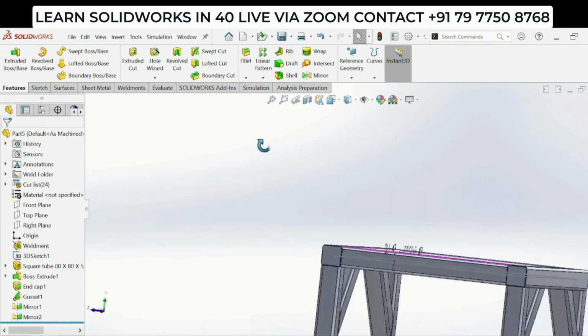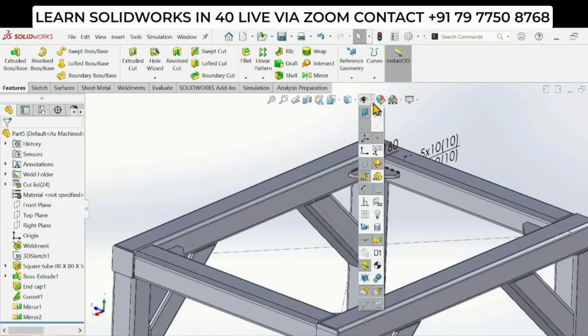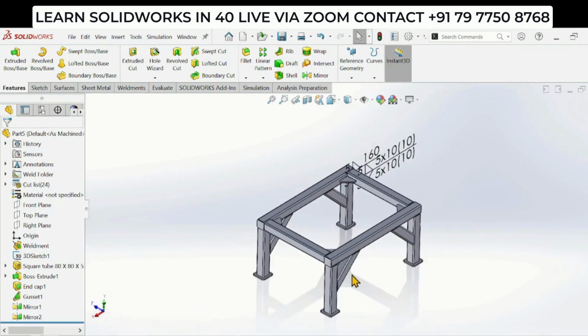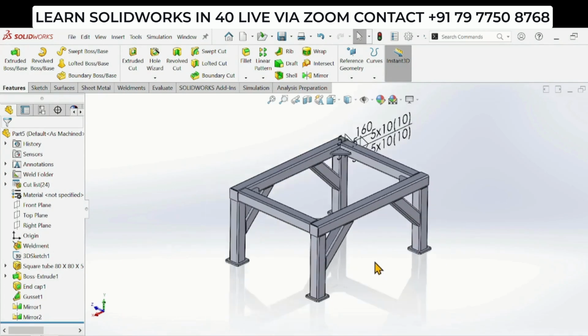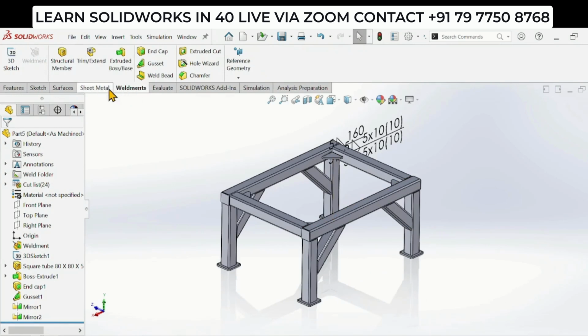I'll show the weld bead, but I'll hide the sketches here. Okay, now our steel structure is done. We used the features like structural member and gusset, end cap, weld bead to create this steel structure.